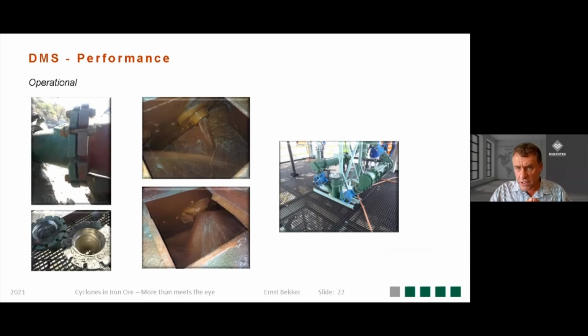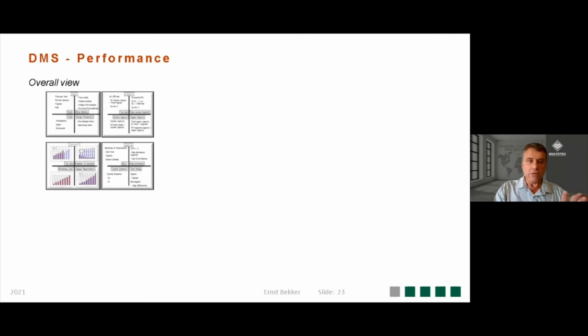On the densification circuit, the pipe densifier, the client battled to maintain density. Only later, when we inspected the system, did we realize that whoever did the installation had an oversight on one of the pipes, and the client lost money during that period of time. Coming back to the comment I made earlier, to see a 0.067 EP is not difficult. So these types of conditions can create a problem in your process, although the cyclone has been selected correctly.